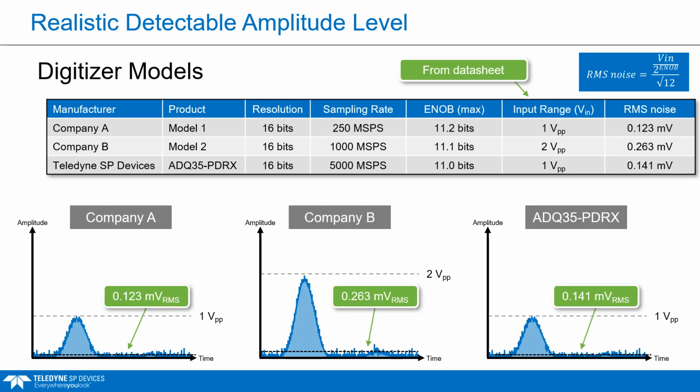The RMS value is an average, so individual noise samples can be higher. Users must set a reasonable trigger level based on their application. Some applications are more forgiving, while others need a good margin to avoid false triggers from noise.